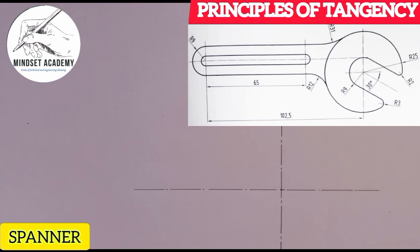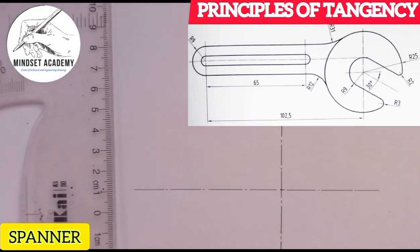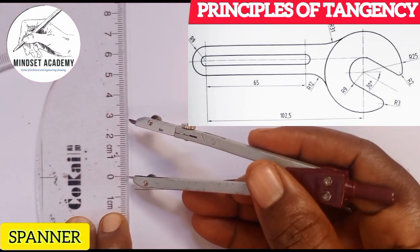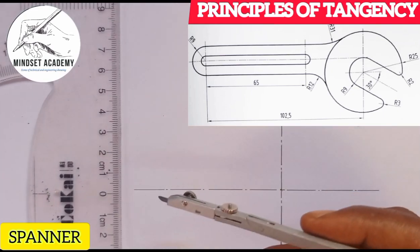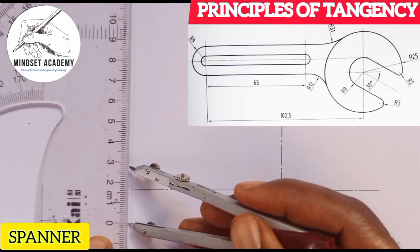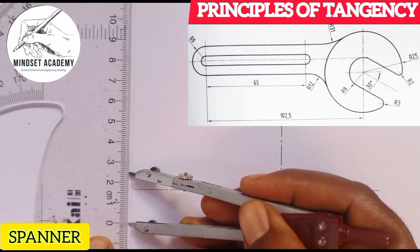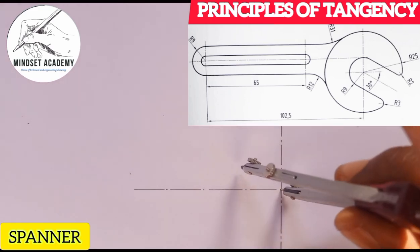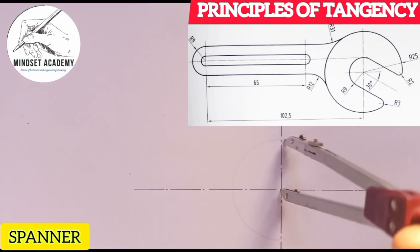Now the next thing is to draw the outer circle. You see this bigger arc here, which is a circle of radius 25. So I'll take my meter rule and measure a radius of 25, from this point 0 to 25 is what we have here. When I place it at this point here, I'm going to draw a circle this way.